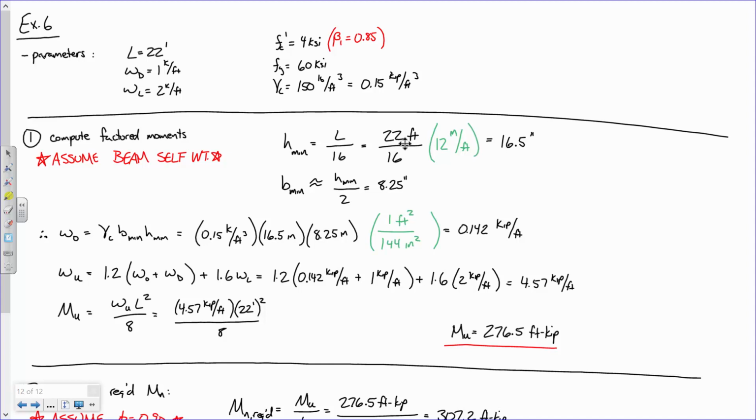We're probably missing the bar. In other words, we assume that the beam weighs about 150 pounds per foot. It's probably heavier, but it's not going to be that big of a deal because, how much does this number really affect the factored load? It affects it, but not too much, so it shouldn't be that big of a deal.